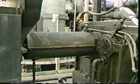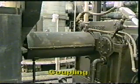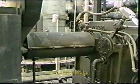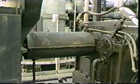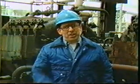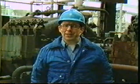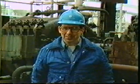The driver is connected to the compressor or gearbox through either a flexible diaphragm coupling or a gear coupling. The coupling allows for small misalignments between the two rotating shafts. And that's a typical centrifugal compressor. Now let's take a closer look at compressor operation.